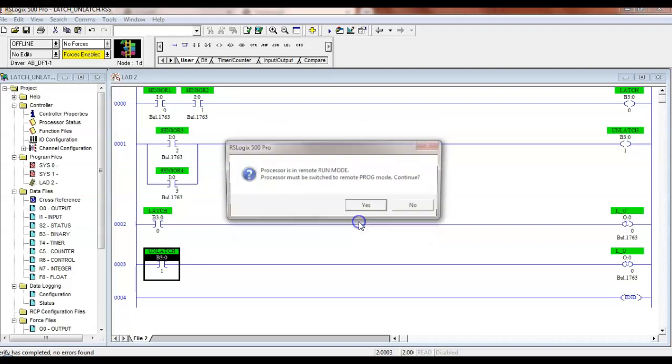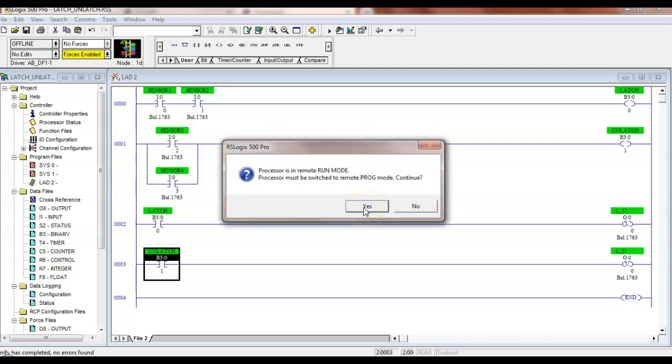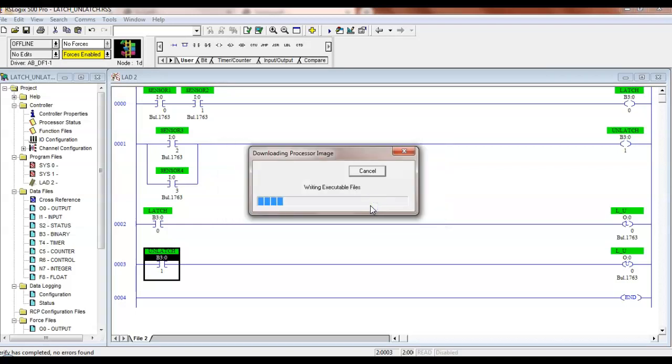So right now I'm going online with it. You can literally create programs offline. You can select a CPU, you can create your whole program from your house. Then you can come in and hook it up to the PLC. If I had to have this sucker hooked up all the time, I'd be in trouble, right? Once I switch this thing to run, you can take that cable out. It's just going to sit there and run the program forever, right? You understand that? Of course, I'm going to switch it into run mode when I get through.